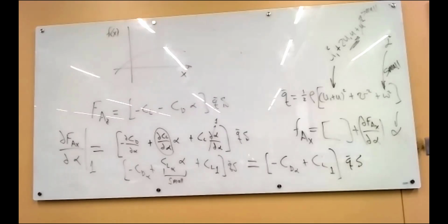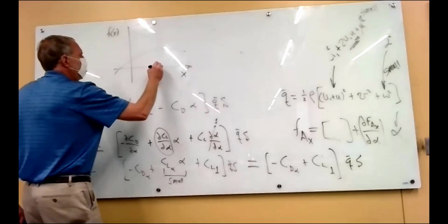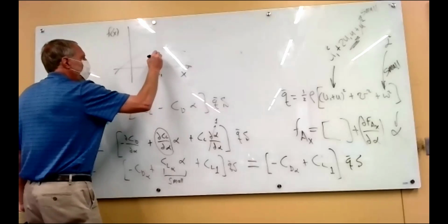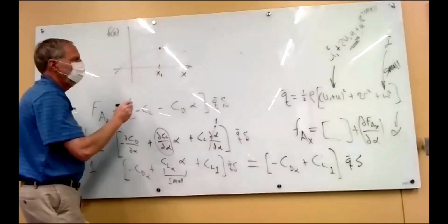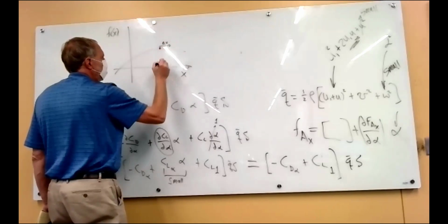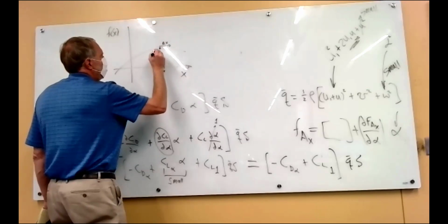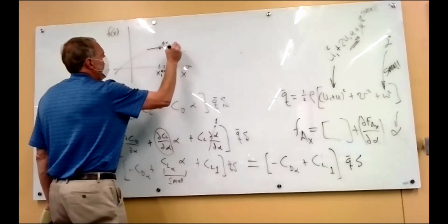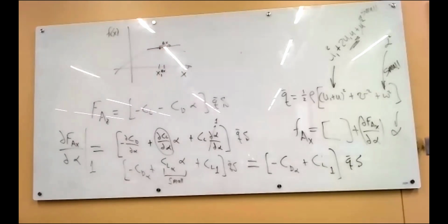Where on the curve do I want the slope? That's what we're really doing here. I'm going to say, here is x1, that's my steady state flight condition, and then I'm looking at a small perturbation, delta x. So I'm going to take my slope and calculate it at the steady state flight and then use that to project to that new position, because that delta x is so small that the curvature doesn't really count so much.